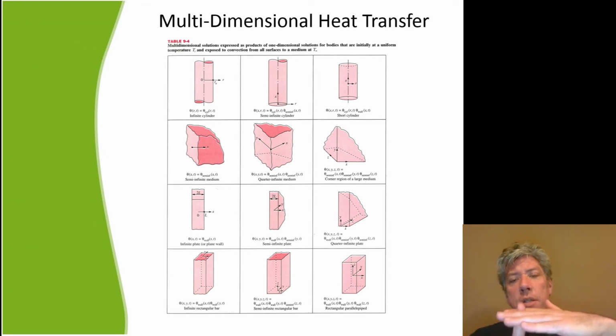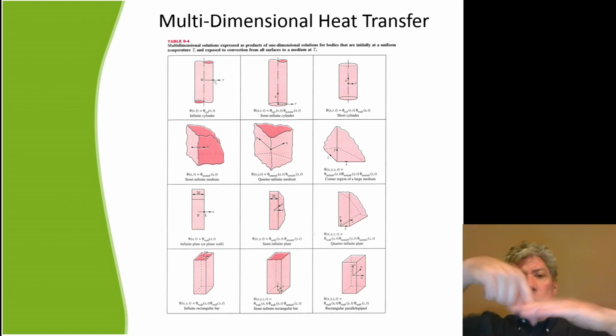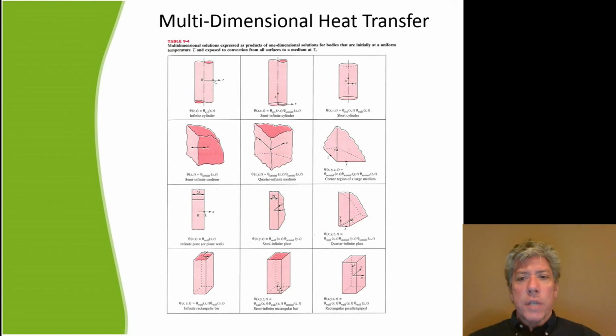And you realize that in the semi-infinite body, heat transfer is into the body, right? Normal to the surface. So now you know there's a direction of heat transfer along the x direction. Now be careful with this. It's not just as simple as whatever the coordinate directions are, that's the direction of heat transfer. Maybe, maybe not.